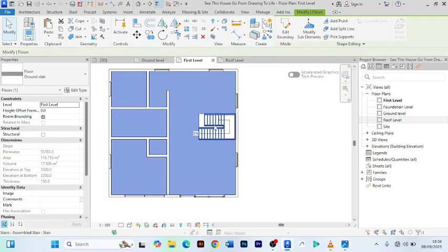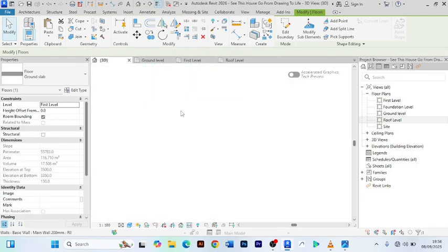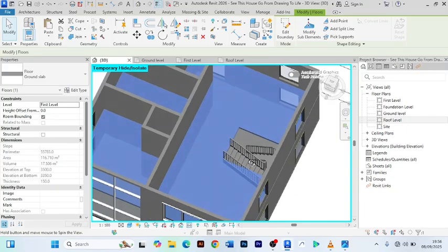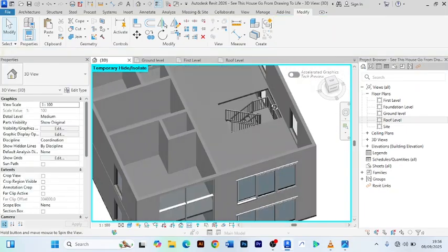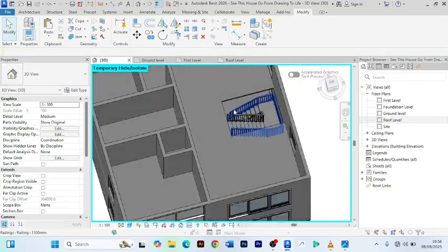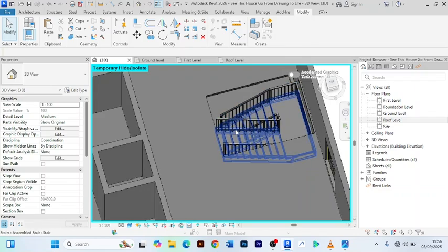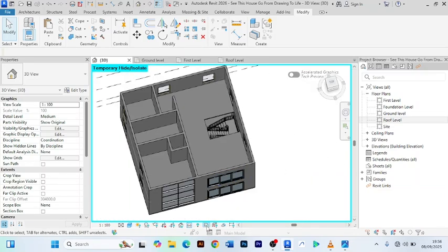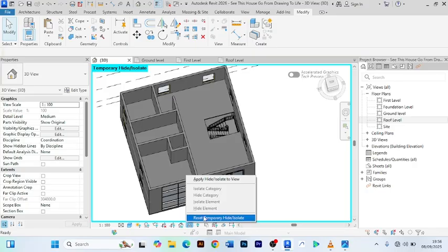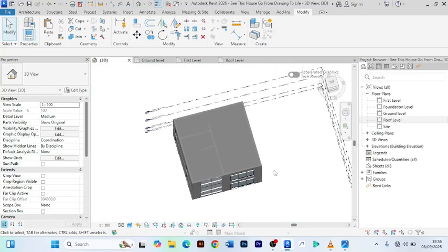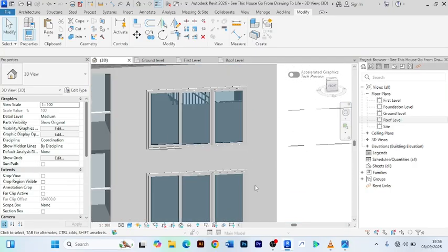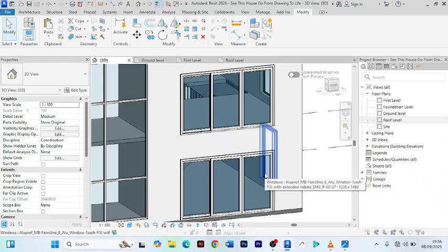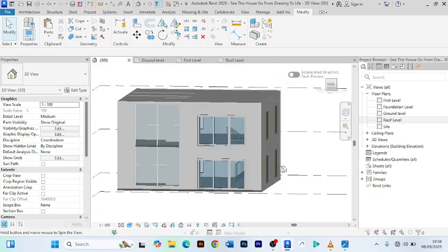The stair is open. When you go to your 3D, you will now see that the stair has been properly opened. You can now come like this all the way from down up to up here without any problems. So now I can simply reset my height, and I think that is it for the stair. Now you know how to create a stair for your house.